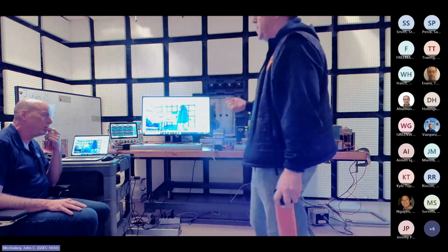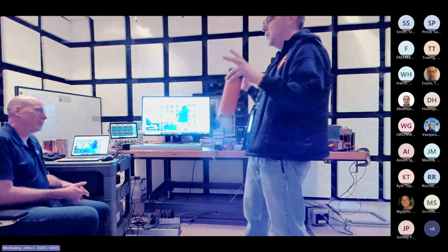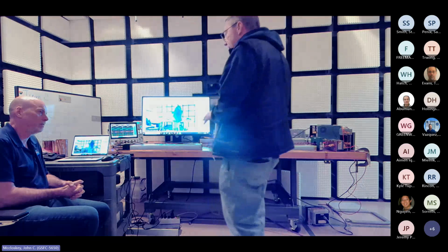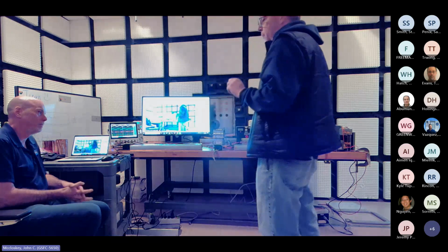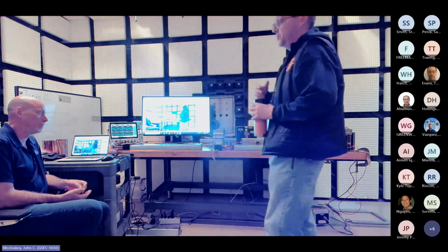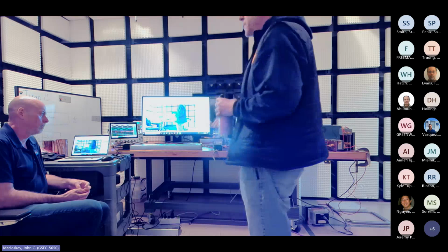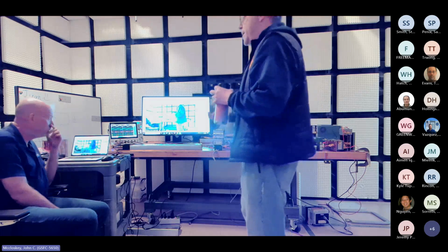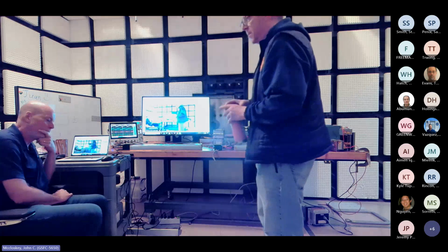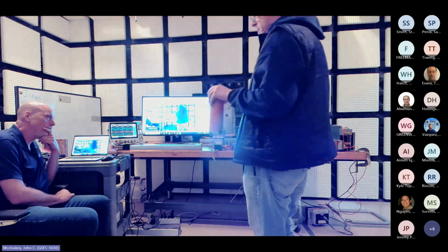With an FFT receiver, you can push that little button and you'll see all harmonics of that thing over a 60 megahertz window. It's an amazing tool to figure out when you have emissions problems and where they're actually coming from, because you can look at it from a persistence aspect, which gives you time domain and frequency domain, and lets you know when that signal is being transmitted and when it's not, sort of like Bluetooth, where it operates at the same frequency, but at a different time.